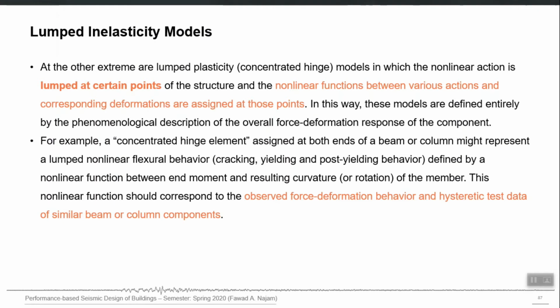You apply load and you will see that some of those small elements will be highly stressed, and that is showing cracking. So you will be able to model the propagation of damage also if you use the continuum model. But here in the lumped approach, you cannot account for the local level failure like cracking explicitly.